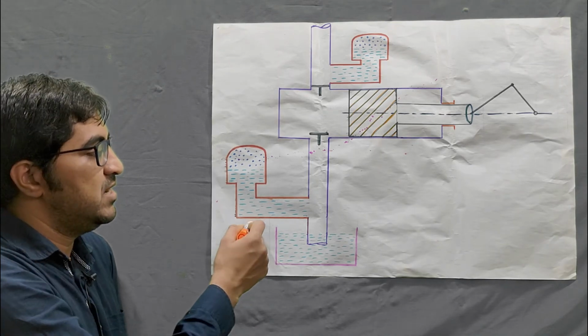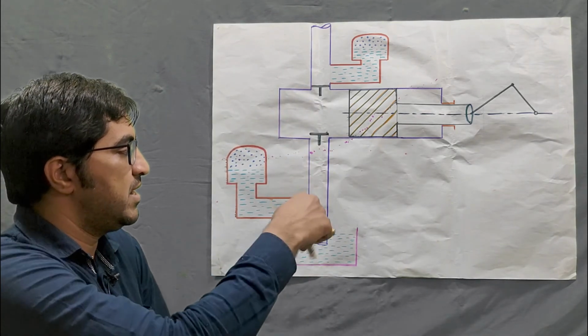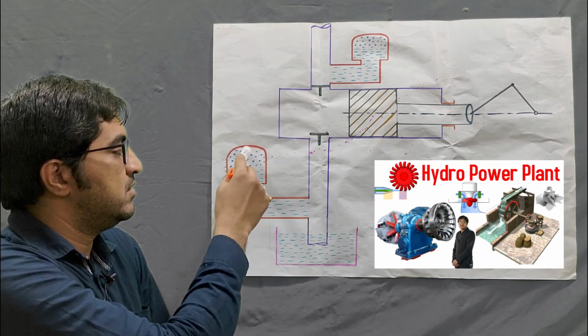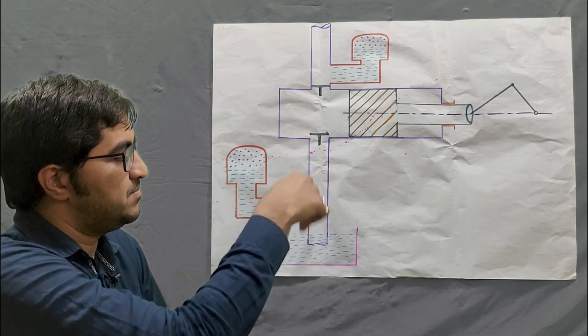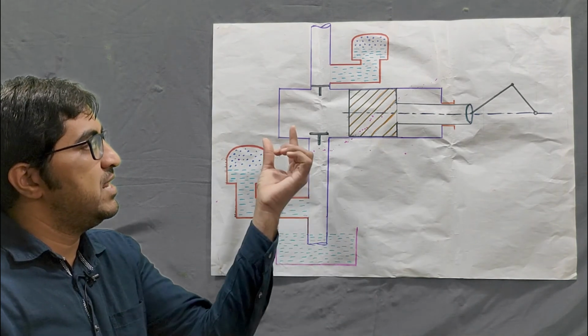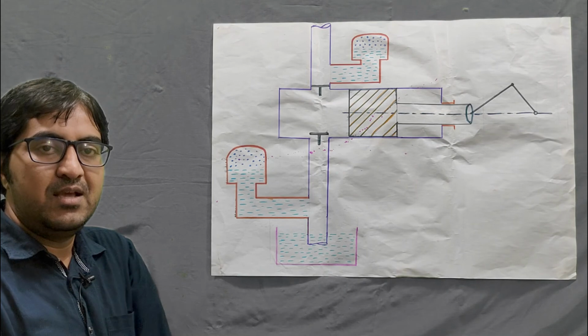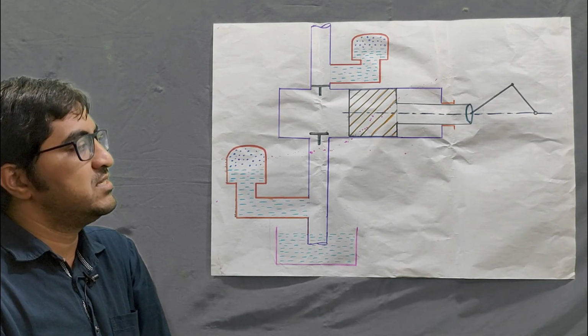This is the basic need of these two air vessels, which are required to fill up the line. Whenever the suction line is empty, at that time the air will expand and the fluid will fill up the suction line. So the suction pipe and delivery pipe are continuously filled with liquid, and we can maintain constant velocity throughout the working of the single acting reciprocating pump.